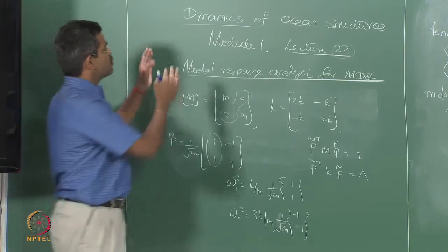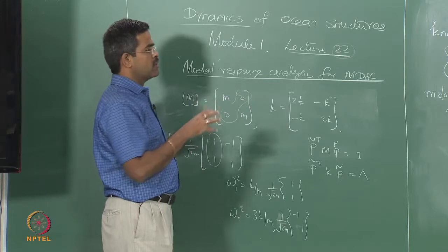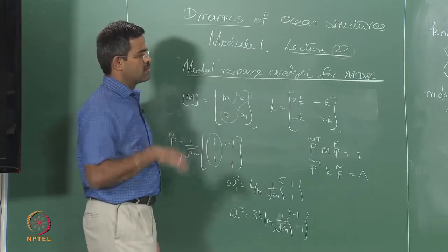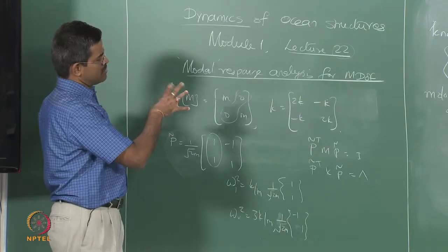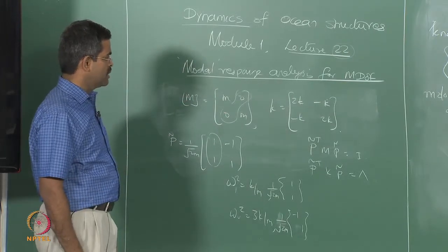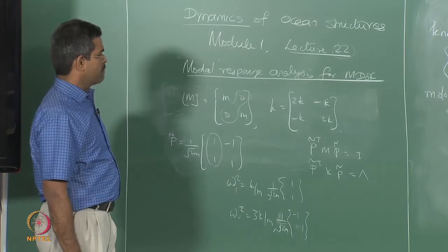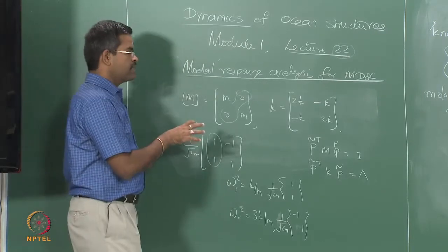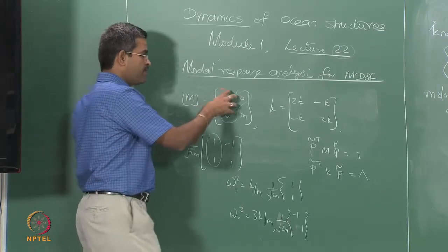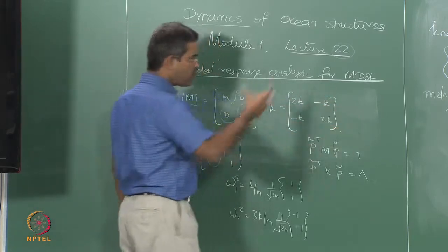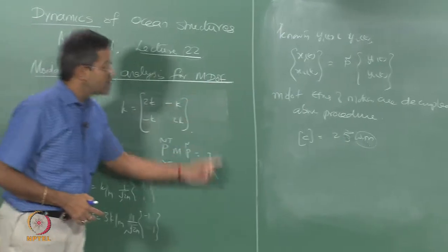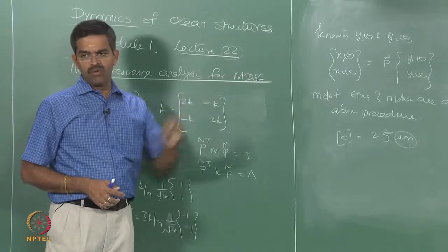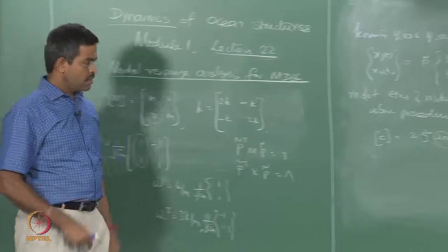But the application to ocean structures in terms of design is very important, which I touched upon in my previous lectures, as well as in my textbook where relevant examples are given on how to relate this to the design concept in dynamics of offshore structures. But we will extend this study in detail to arrive at m, k, c and of course x of t, that is the vector, for a given problem whose f of t is taken from earthquake load, wave load, current load, etc., a real life problem.